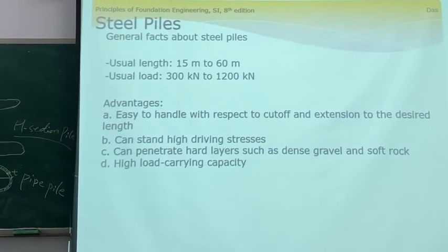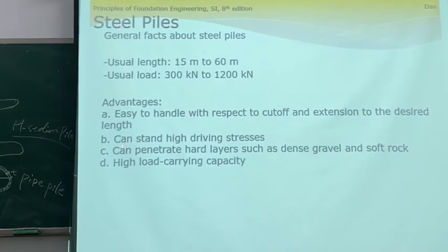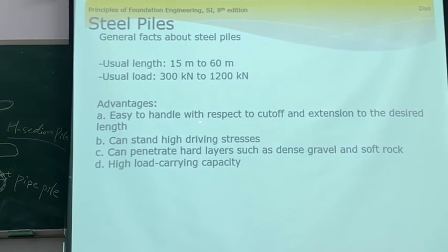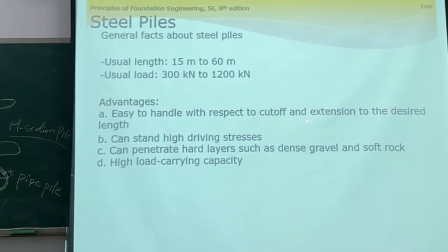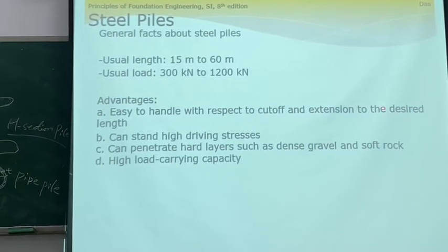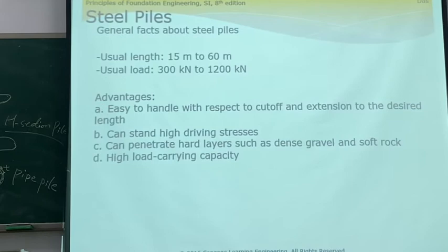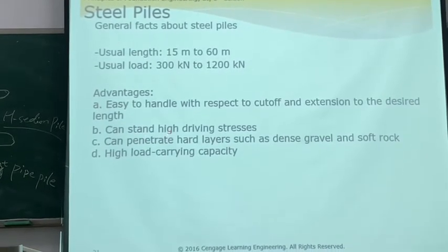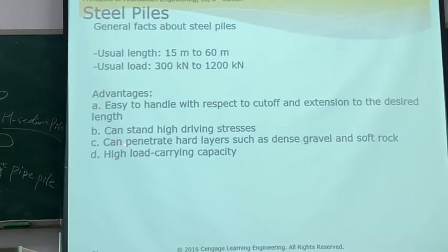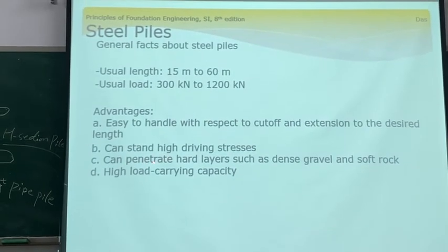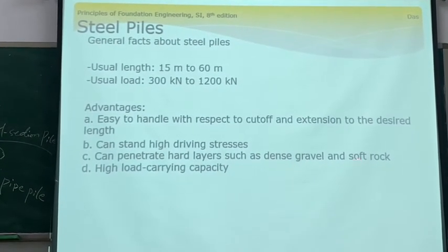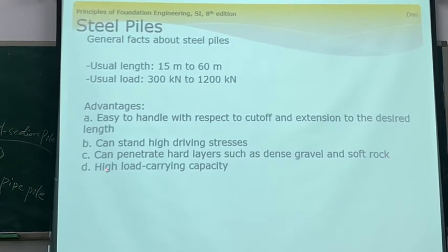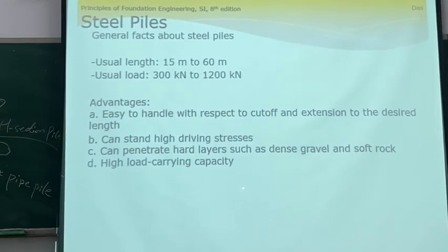Okay? So the advantages of the steel pile are that it is easy to handle with respect to cut off and extensions, it can stand high driving stresses, and it can penetrate hard layers such as dense gravel or soft rock. It has high load carrying capacity.